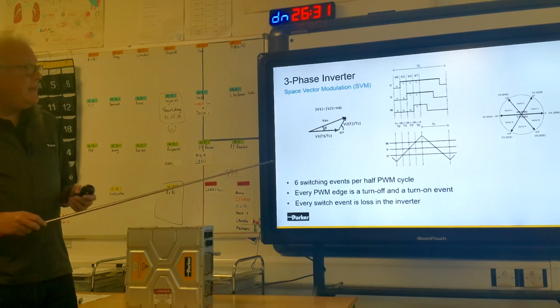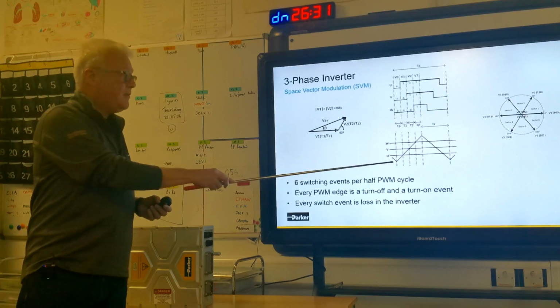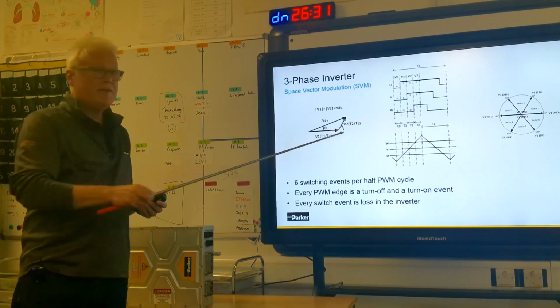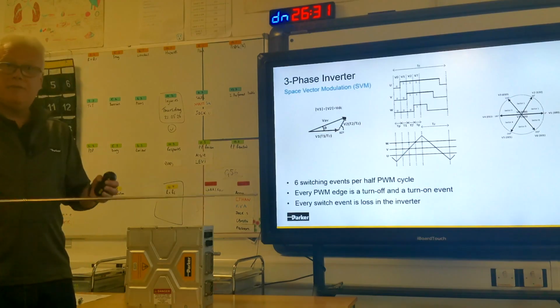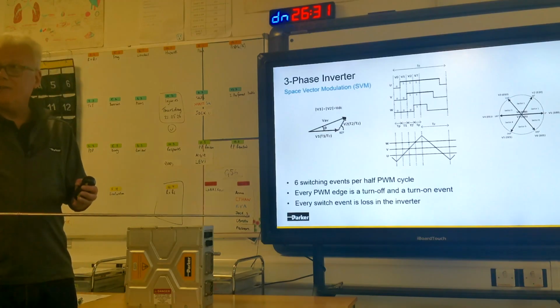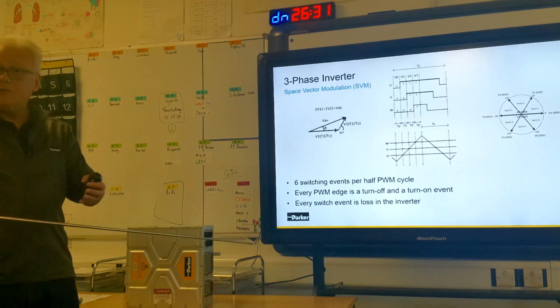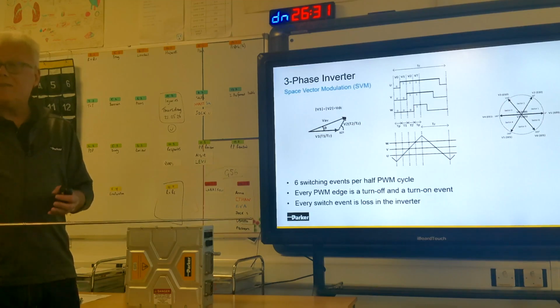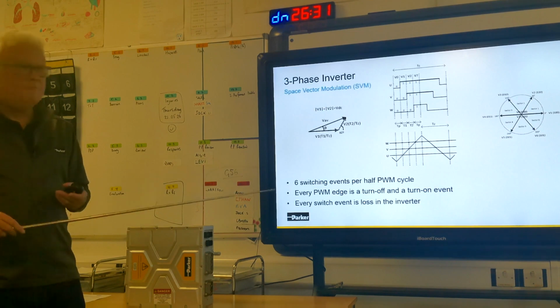And you can do this. You can get these general timer units to trigger interrupts at the top and the bottom of the carrier waves that you can then use to trigger another peripheral, which would be the analog to digital converters. And when you look at those signals, you will see nice sine waves of current. You won't see any ripple current, which is kind of good.